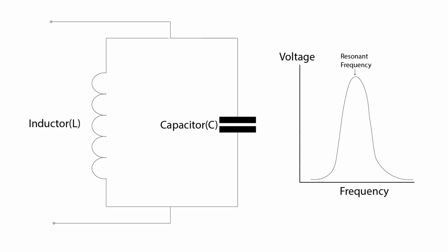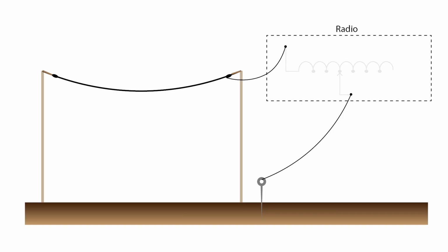So this is where our inductor becomes important. Now, the author's design uses a coil wound round a plastic bottle, like a pill or water bottle. And he then puts periodic tap points into that coil. These are places where we can attach the other side of the circuit so we can easily create coils of various lengths. And this acts as a rudimentary tuning mechanism.